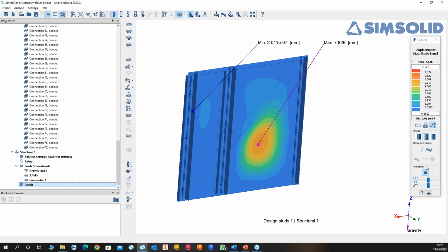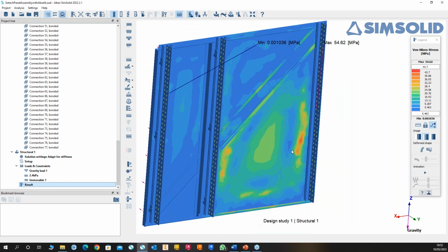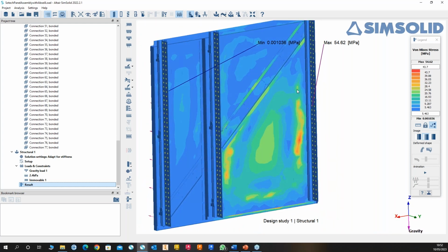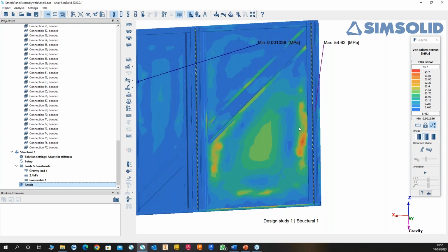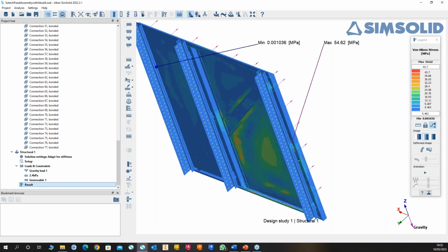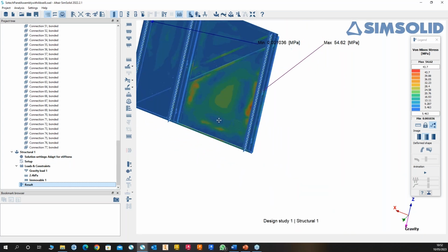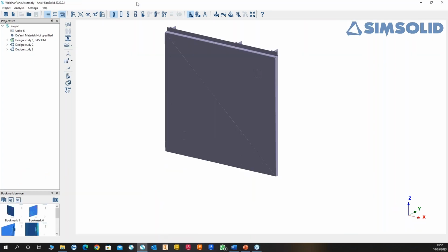Now, if I stop the video and we look at the stresses, you see the stresses that are shown here. Because we've run it based on stiffness, I don't quite agree with this. This is where you need to change it to adapt for stress and run it for stress, because I'm expecting the stress to be mainly around these areas on the hooks, where it's all over the place. It's been scattered. So I've already run an analysis based on adapt for stress.